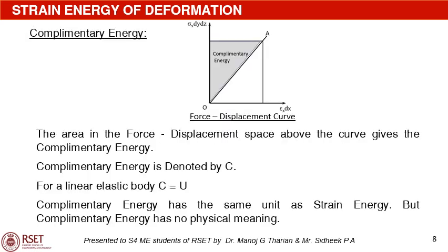I will introduce you to the concept of complementary energy. The force deflection space is divided by the force displacement curve into 2 regions. One is the area beneath the curve OA, and the second is the area above the curve OA.